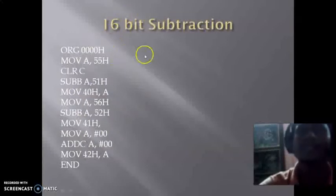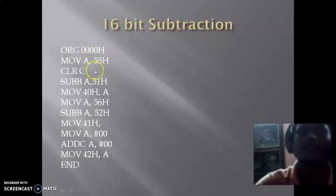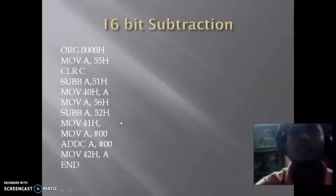Next is a 16-bit subtraction, and here basically 55H is stored into the accumulator first. Similarly, we are doing the task. This is the lower byte of data, 55 and 51, that is the lower byte of the two data, and 56 and 52 are the upper bytes of these two data. And here is what is happening.